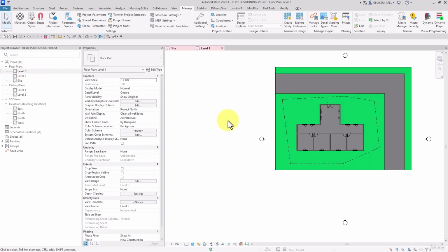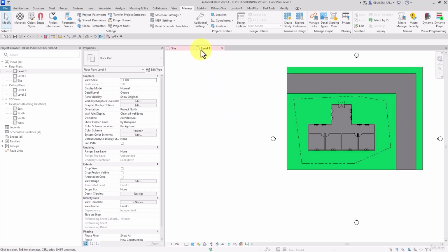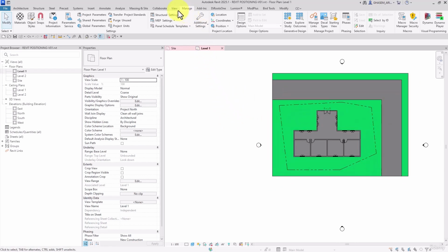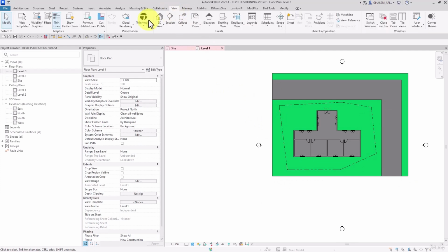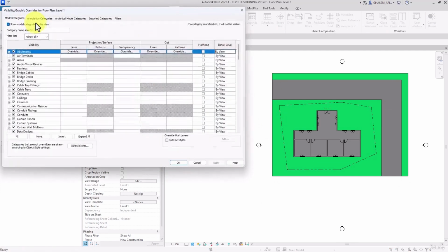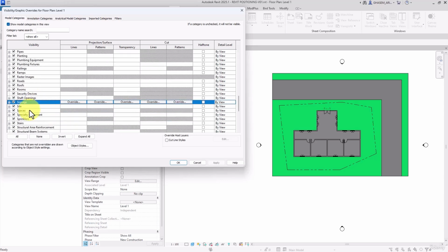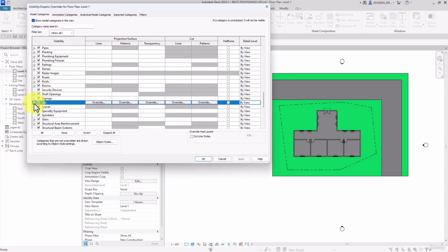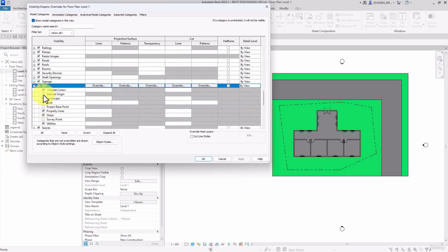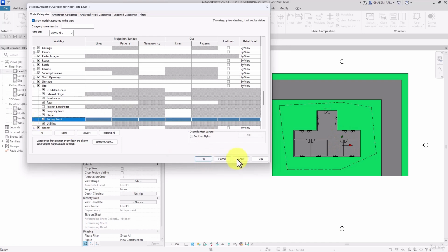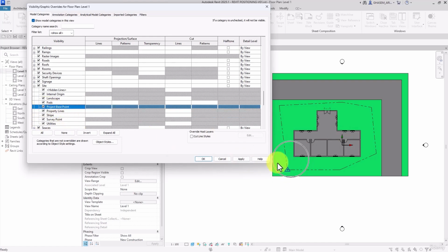So if you open the 2D views and then you wanted to show these points, firstly you open them, then from View tab, Visibility Graphics, and then we should search for site and just open the subcategories. Watch this, internal origin, check it out to show it, survey point, and also project base point. We can show them this way in the scene.